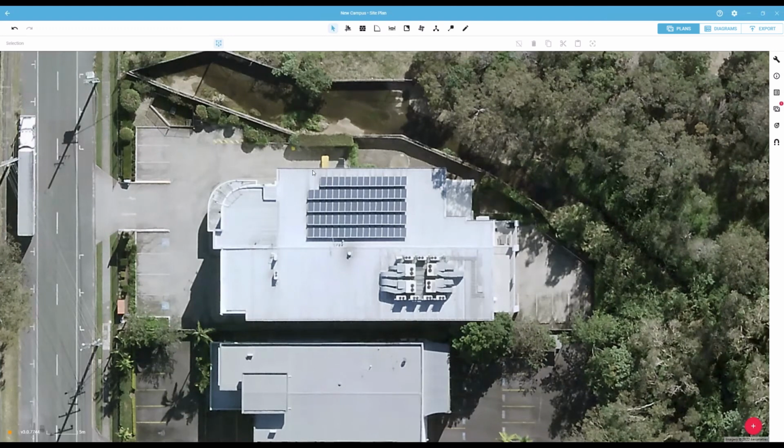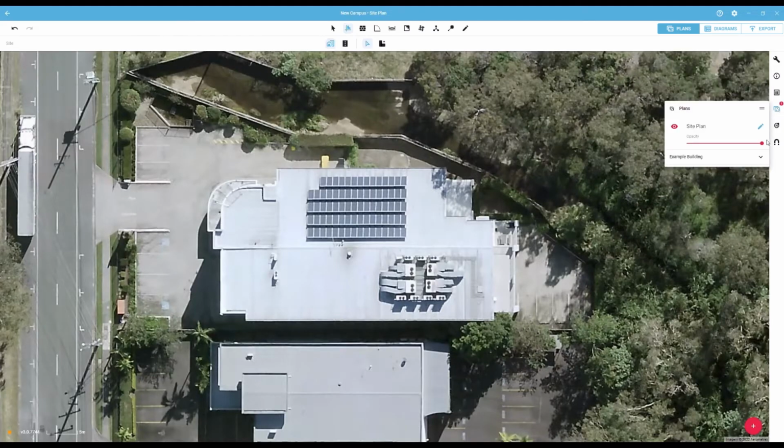To get started creating a site plan, we will import our building footprints by selecting the Site tool. In the sub-toolbar, you have the Building Footprints option, which gives us the option for automatically importing building footprints from your floor plans. This works by using the interior zone from your floor plan to create the outlines for your building and place them on the site plan.